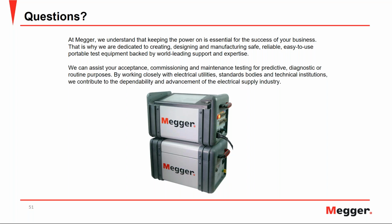Sure, a good example is when you're testing a three-winding transformer, right? If you remember, and you will get a copy of the presentation, and you can look at those diagrams in PowerDB as well. When Charles was showing how to connect to a two-winding transformer, you have three electrodes: your high voltage windings, your low voltage windings, and ground. If you have a transformer with a tertiary, then you have an extra electrode. And PowerDB will guide you with connections as well, but you will use the blue lead to connect the extra electrodes in all the three basic measurements that you have to perform.